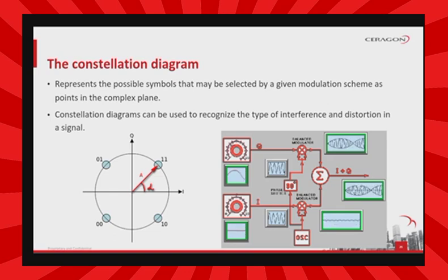This signal is for all intents and purposes a double sideband signal, DSB, with or without a carrier, reduced. This method of modulation has the advantage of reducing or eliminating intermodulation interference caused by a continuous carrier near the modulation sidebands.